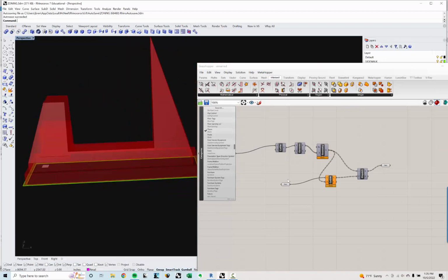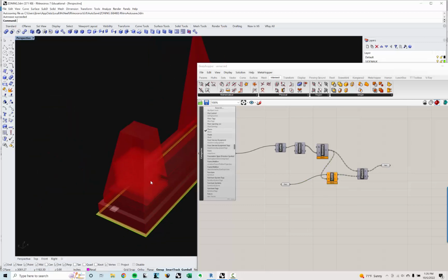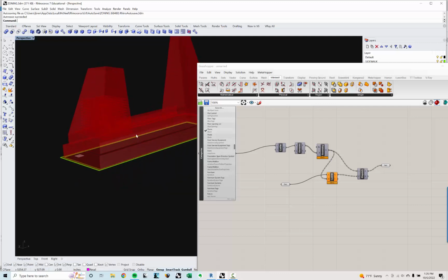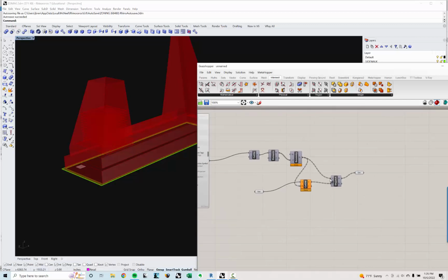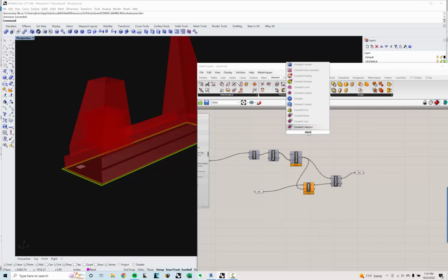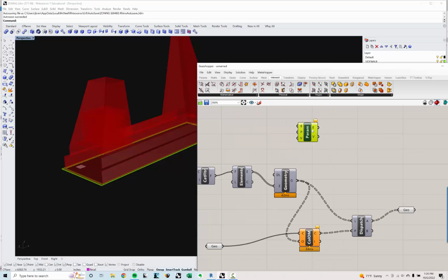Okay, cool. So now that we've got that method of modeling things in Revit and checking the zoning compliance, what I want to do is I want to start actually checking for program counts. So I'm going to go and I'm going to come into the element, and I'm going to use the element parameter category, right? And I'm going to take my element.